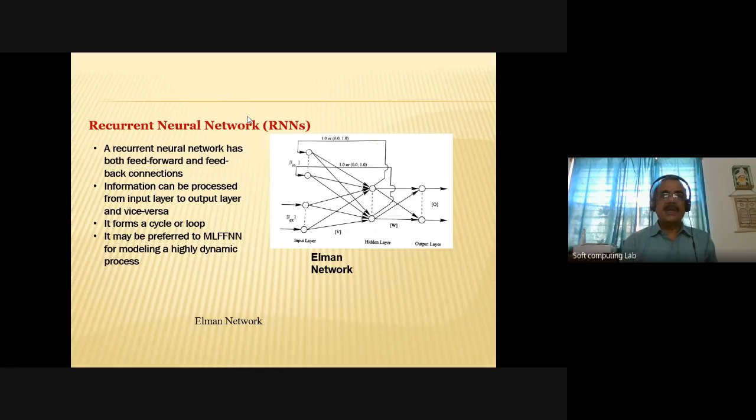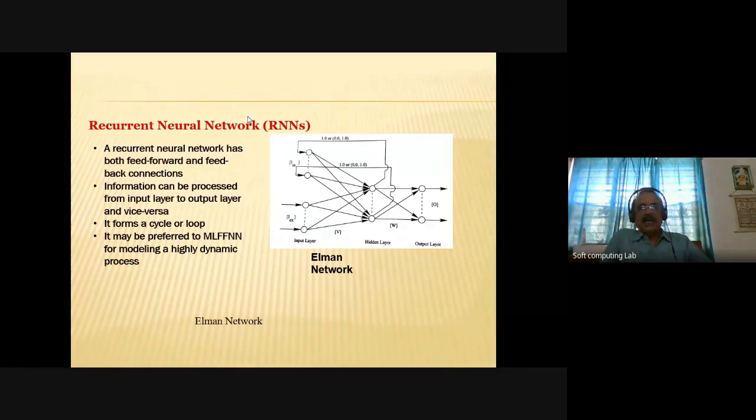So I want to find out a very good surface finish on the turned part, the straight turning job I am doing on a lathe, and the inputs are cutting speed, feed, and depth of cut, and the output is nothing but the surface roughness of the turned surface. Now, supposing that an operator has selected cutting speed, feed, and depth of cut while doing turning.